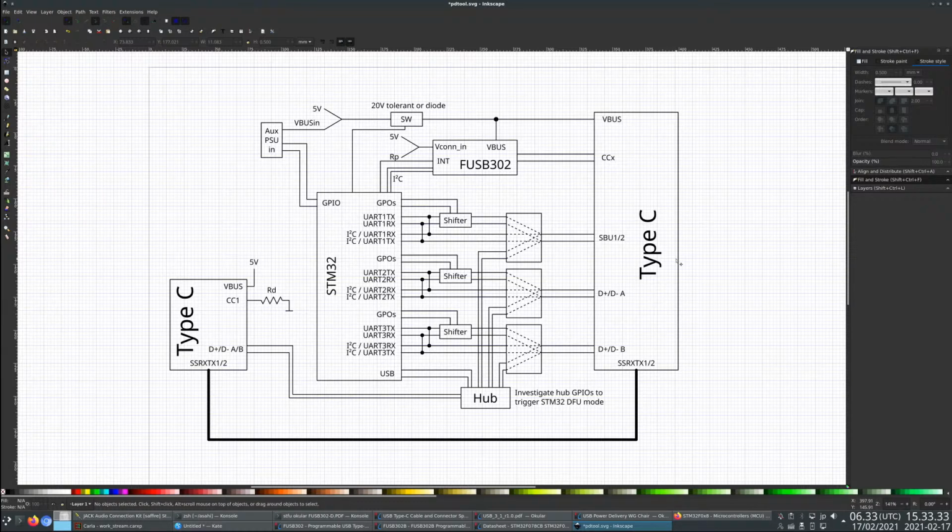So that's it sort of like, if you're going to use it as a pass-through, then I want you to actually wire a wire through as a sort of implicit expression of intent that you know what you're doing. You mean jumper it and not connect it to anything else, but we need to supply this somehow, right? This needs 5 volts, so if we just jumper 5 volts VBus, then what's the STM32 going to do? I mean, this needs 5 volts to run, right?